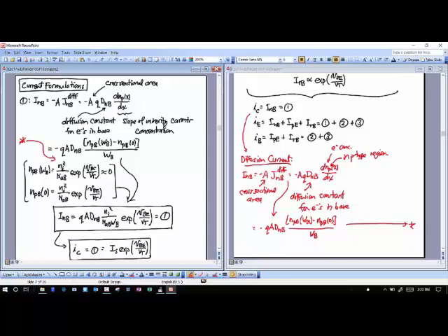But in much nicer handwriting here, you see all of this here, all those equations that I just wrote there, and then finally the equation for the electron current going into the base. Okay? Which I am saying is this one current control, is this one thing, right? Is the current 1. Okay? And so that is approximately the number of electrons that make it to the collector. It won't be exactly because I'm going to lose some to the base. Right?